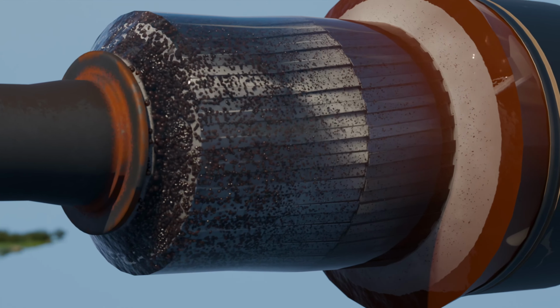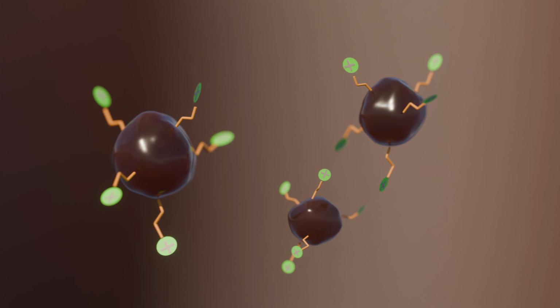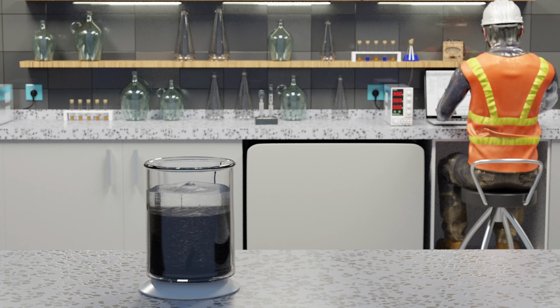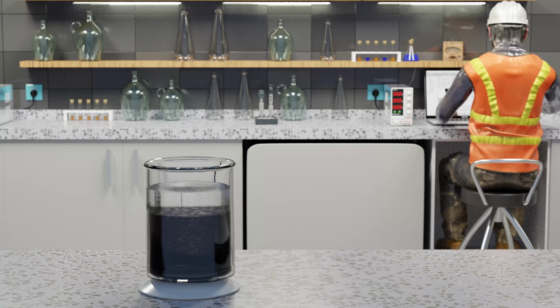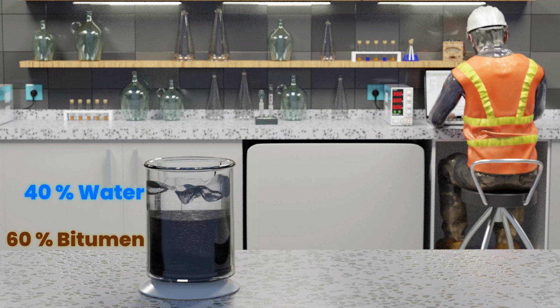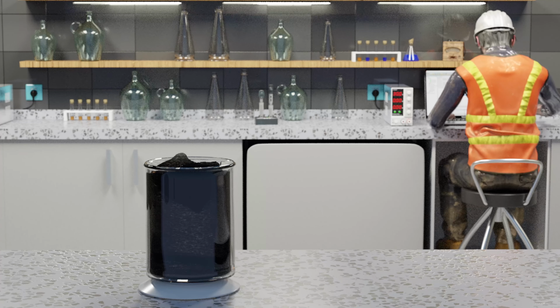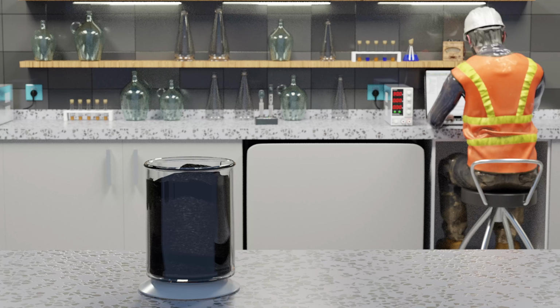Bitumen emulsion is a suspension of bitumen droplets in water. The manufacturing process transforms soft grades of bitumen into tiny droplets roughly the size of 5 micrometers, and an emulsifying agent is added to create a stable emulsion and provide each droplet with the same charge. Emulsions used for stabilizing have a typical bitumen to water ratio of 60% bitumen and 40% water. The emulsion production process is complex, requiring expertise in chemistry and chemical engineering.